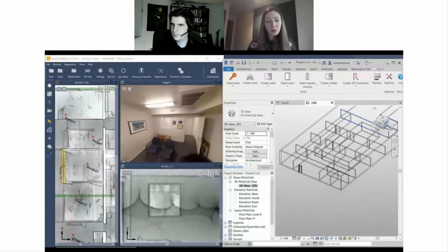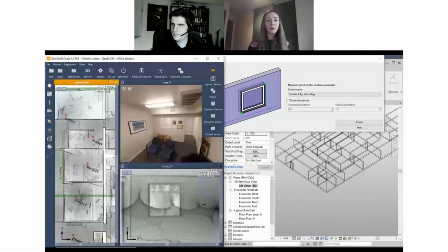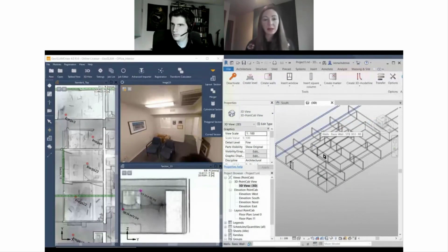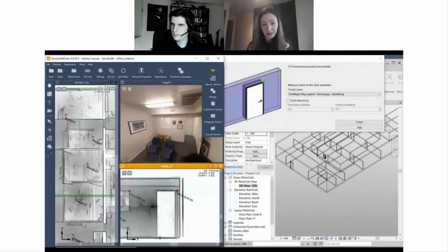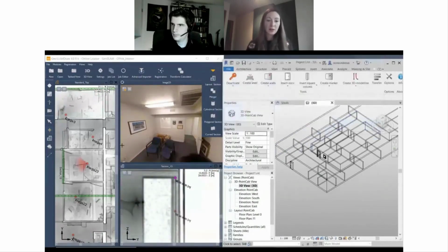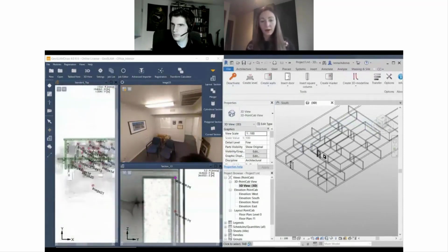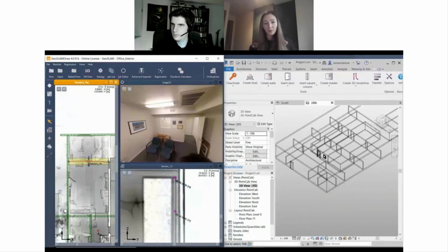When it comes to accuracy and the level of detail, generally we are within LOD 300 with the GeoSLAM data, and past that other technology can supplement the scans, like terrestrial scanners. And the level of accuracy scale is 30, that defines the local level of accuracy from 5 to 15 millimeters.